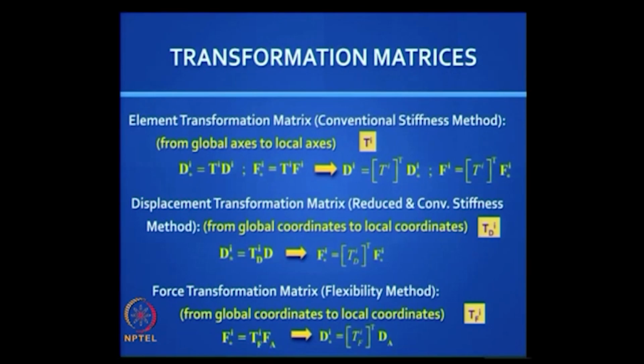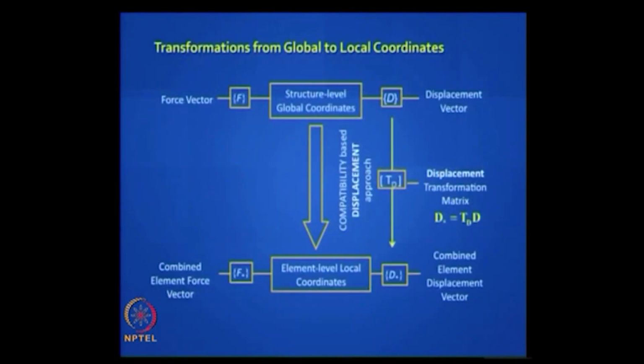Now the inverse of those matrices helps you switch from the element level, the local level, to the global level, and there is a principle, you do not need to do the inverse, there is a principle called the contragradient principle, a beautiful principle which we will look at shortly. Right, so let us look at these transformations.